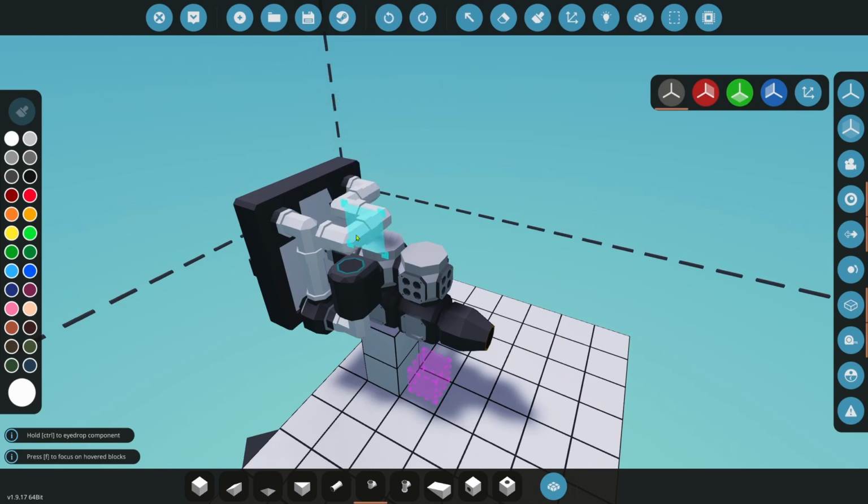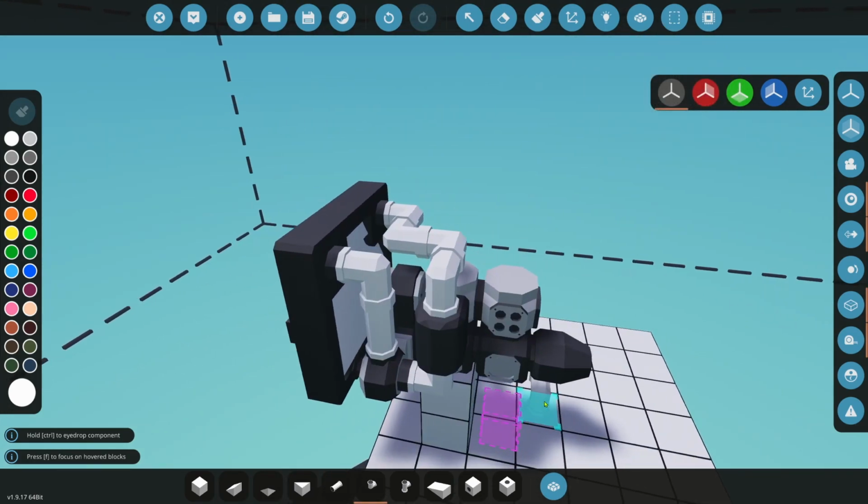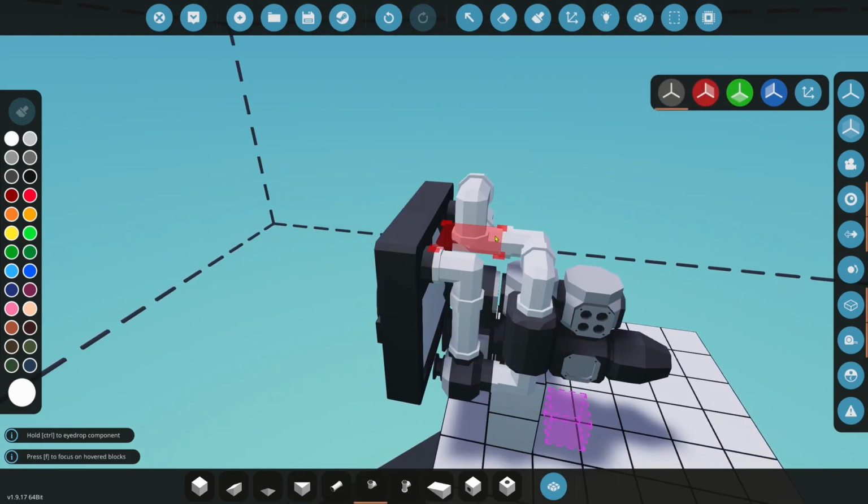If you watch the cooling tutorial, you'll see some of the best systems. The shorter the run of your pipes, the more efficient it is going to be. So keep that in mind. The shorter the run. So for example, if I wanted this really short, we could try to put it on top so it wasn't running too far. But the fewer the pipes you have, the better the flow rates you're going to get, the better the cooling you're going to have.